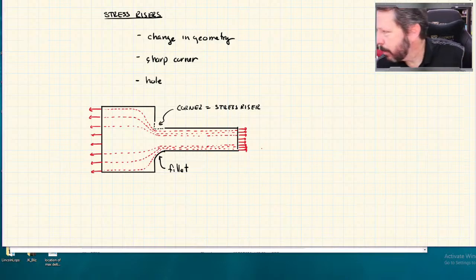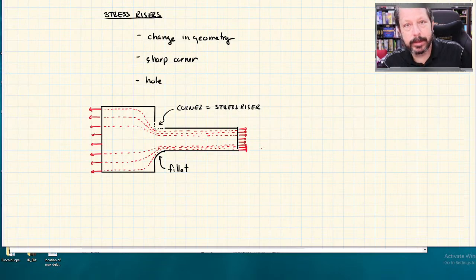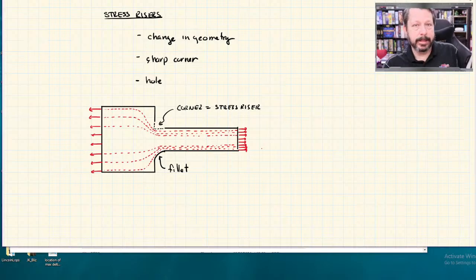So I think the first problem we're going to do, like your dog bone simulation lab, that's lab 1, right? I gave you freedom to make whatever kind of dog bone specimen you wanted in SolidWorks. There is a standard ASTM shape for the dog bone specimen, and that shape has been optimized to reduce as much as possible these stress concentration factors.